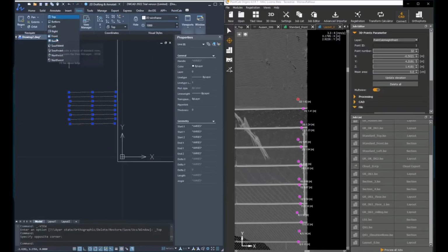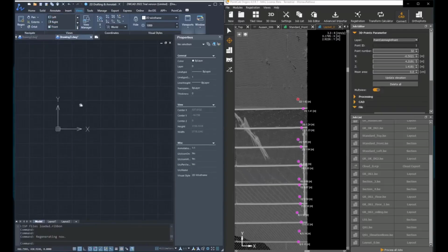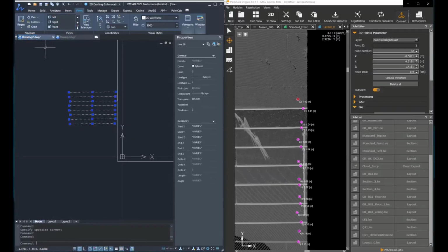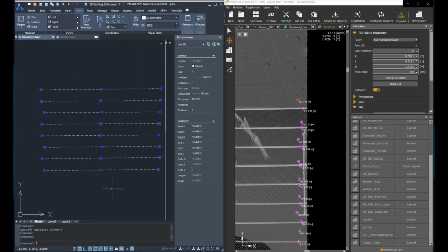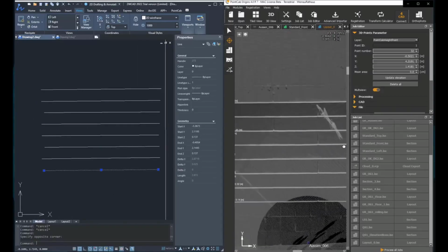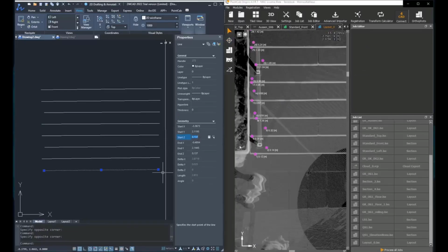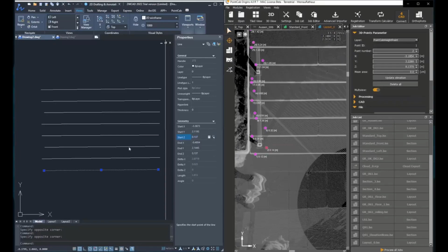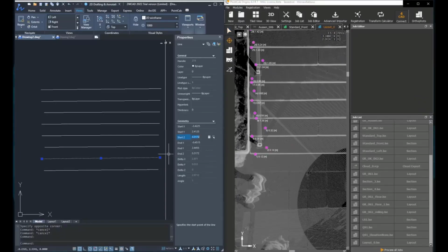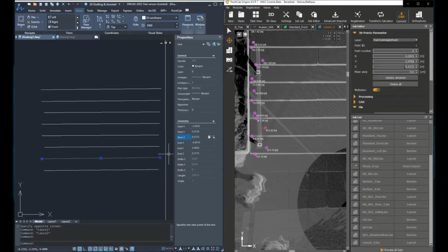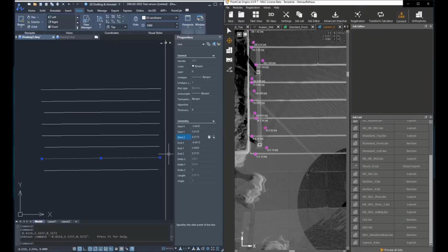we can go in the front view. And then you can see that the stairs were created at a different height, and the height was taken from the second picked point and not from the first, because sometimes it can be that we are clicking at a different height, so this allows a more precise transfer of the coordinates.